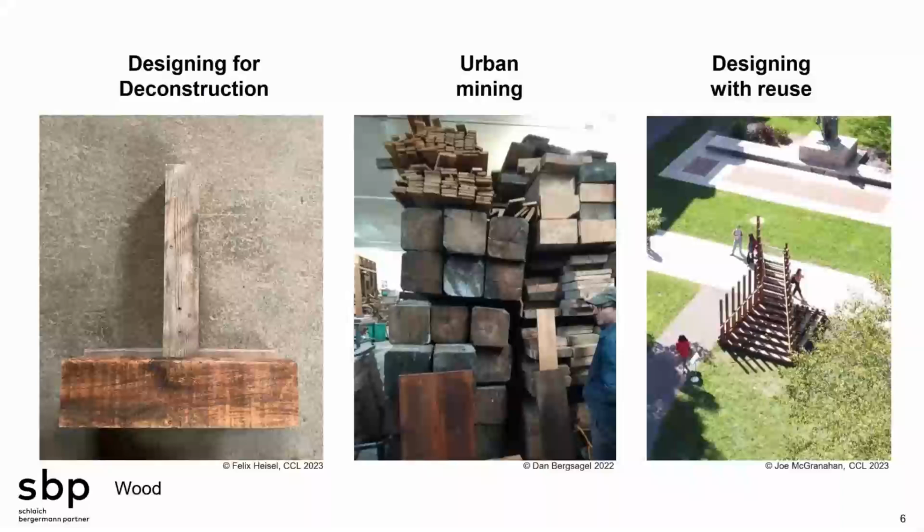However, at the Circular Construction Lab, we were dealing with designing for deconstruction for one of the projects Felix showed previously, and there are still some structural challenges with considering screws and fasteners that can be removed and reinstalled again. When we design wood screwed connections, we only design them according to rules that they're installed once. We don't think about removing them, reusing the same fastener, and using the same location.